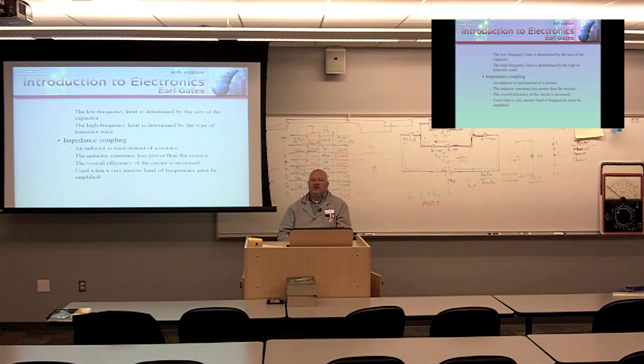The low frequency limit of the audio circuit is going to be determined by the physical size of the capacitor. The high frequency limit is going to be determined by the type of transistor used. Because remember, transistor data sheets show what the maximum usable frequency is. All transistors are not created equal.